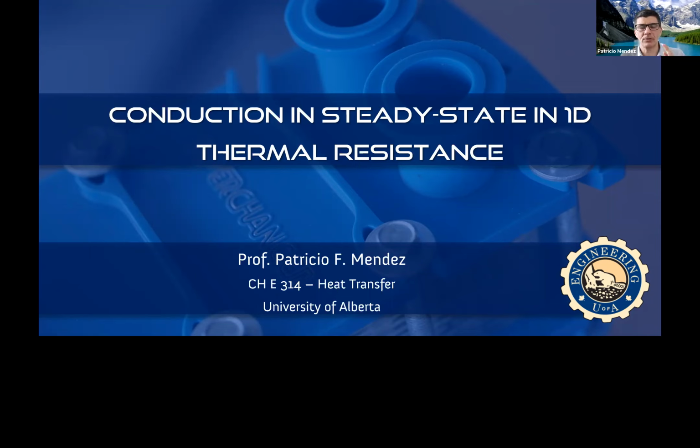And we talked about conduction in 1D. So the problem became steady state, no more derivatives against time, but we had derivatives in space. If the problem is 1D, no problem, because it goes back to an ordinary differential equation. Now, in this case, it would be a second order differential equation, right?